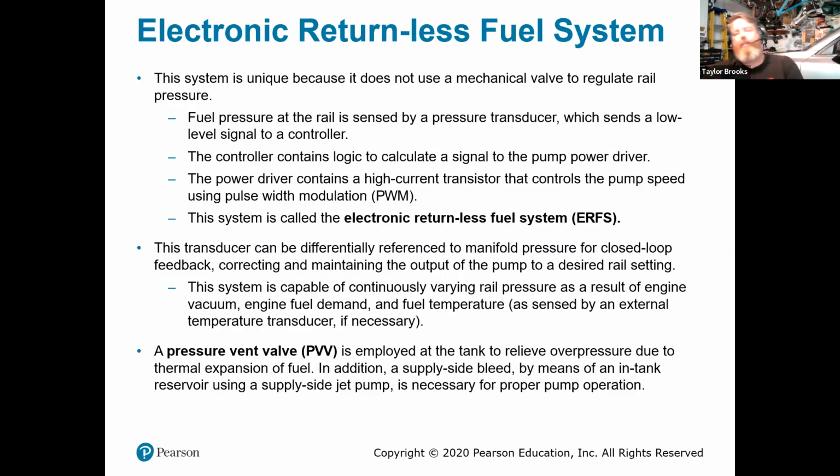Now, what a lot of manufacturers have gone to is returnless style systems, and it makes a lot of sense. The benefit to a return system is you're cooling all the fuel system components. You're cooling everything down because you're using anywhere between 60 and 80% of the fuel delivered to the engine. The other fuel that is sent back to the tank acts as basically a cooling system to bring that heat back to the tank.